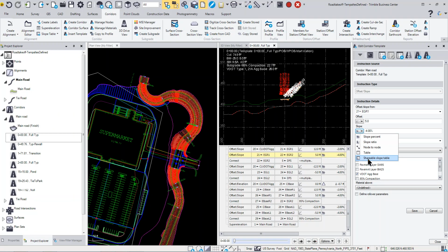And you can view the created slope table line that gets generated in a super elevation diagram. Typically, this is used commonly during road surface rehabilitation and to enter the surveyed slopes of the road.